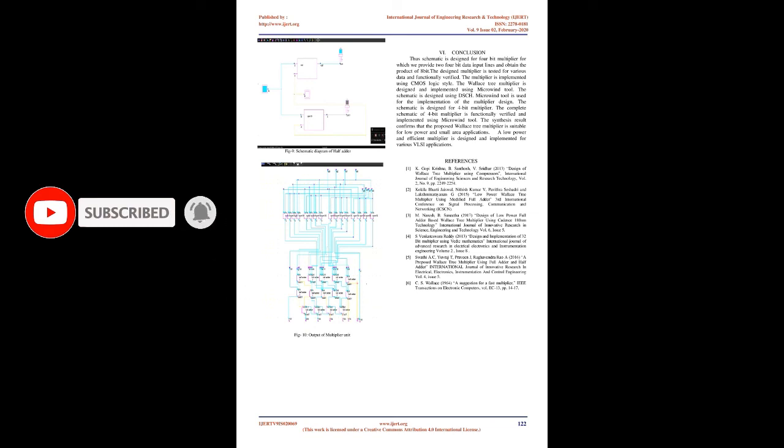Microwind supports the back-end design of circuits. The user can design digital circuits and compile using a Verilog file. Microwind automatically generates an error-free CMOS layout, although this place and route is not optimized enough, as we do not indulge in complex place and route algorithms. The user can also create a CMOS layout of their own, compiling one-line Verilog syntax or custom building the layouts by manual drawing. These layouts can be verified using the inbuilt mixed-signal simulator and analyzed for DRC, crosstalk, delays, 2D cross-section, 3D view, etc.